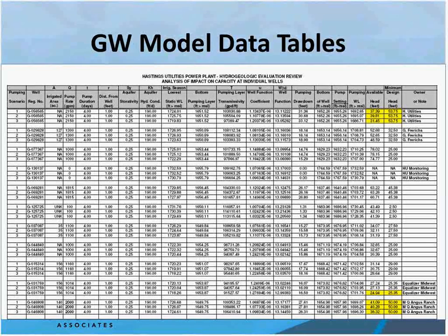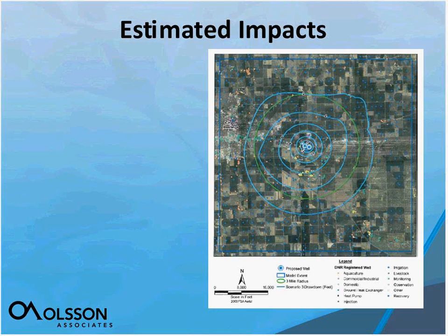Again, this is just a bunch of numbers that we put together to identify the loss in yield for each of those wells, which could be irrigation or industrial wells. The bottom line was that we saw the estimated impacts in the area to be anywhere from 2 to 17 feet, with both those wells running at the capacity required throughout the year to keep that power plant running.